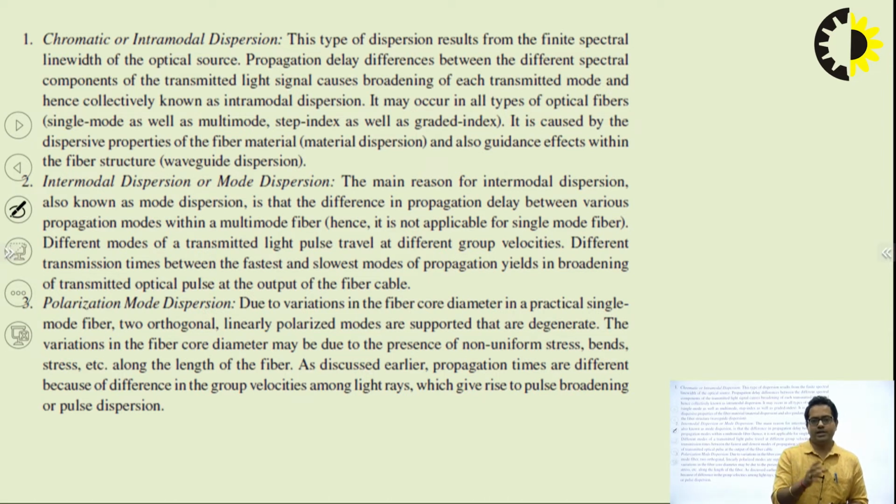Within that line width there are multiple frequencies, and as they travel through the optical fiber they have different velocities as they face the refractive index of the core. This leads to a spreading or broadening of each transmitted mode, and collectively they form the phenomenon known as intramodal dispersion.